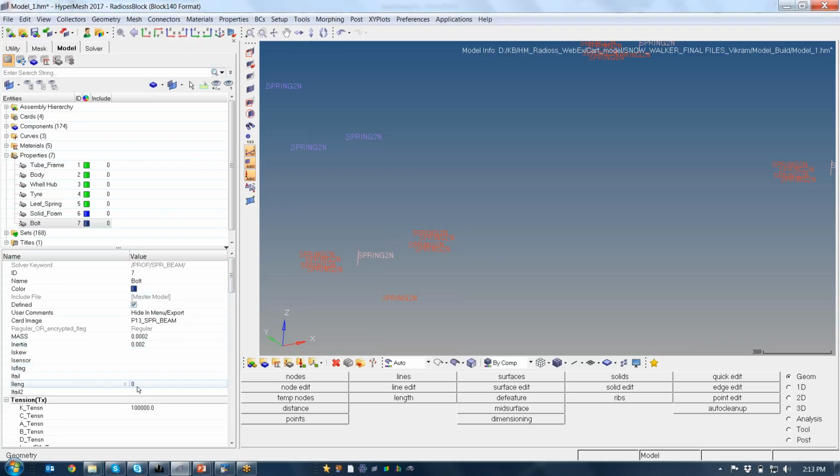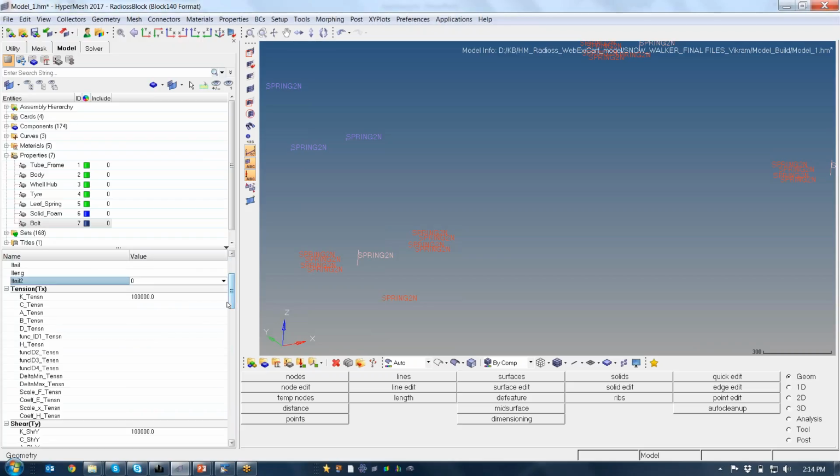Now, as I was saying, there are different failure options. We have the failure options here. By default, it is by displacement, with force as a criterion and energy as a criterion. We'll put the limiting values in these directions, in delta min and delta max.